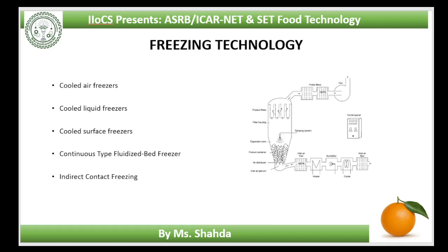Fluidized bed freezers are modified blast freezers in which air at between -25°C and -35°C is passed at a high velocity of 2 to 6 meters per second through a 2 to 13 centimeter bed of food contained on a perforated tray or conveyor belt. In some designs, there are two stages. After the initial rapid freezing in a shallow bed to produce an ice glaze on the surface of the food, freezing is completed on a second belt in beds 10 to 15 cm deep. The formation of a glaze is useful for fruit pieces and other products that have a tendency to clump together.